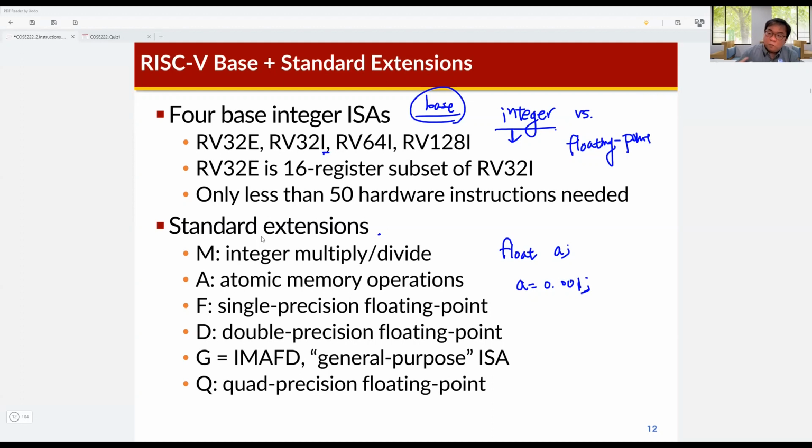If a processor just supports the integer type ISA, then floating point computations are converted into integer type computations. For example, the floating point type additions are converted into integer type additions that take many lines.